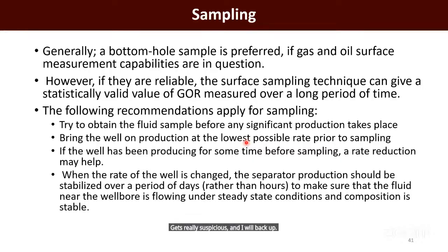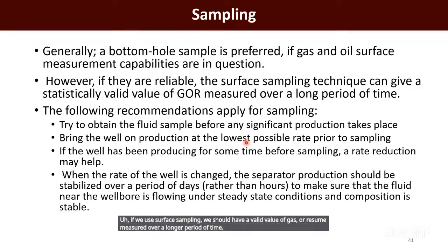Generally, like mentioned, bottom hole sampling is preferred. However, if we use surface sampling, we should have a valid value of gas oil ratio measured over a longer period of time. So also we have a recommendation.